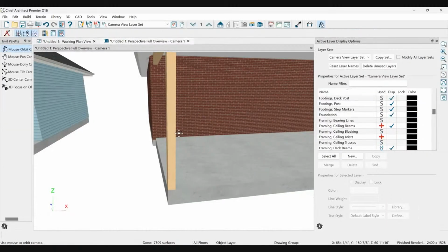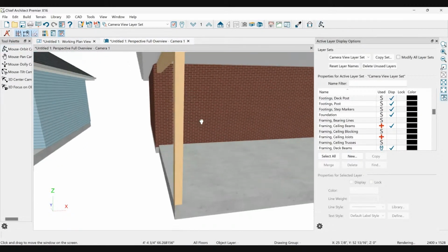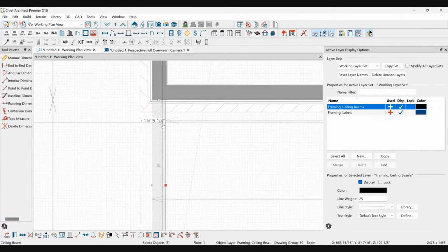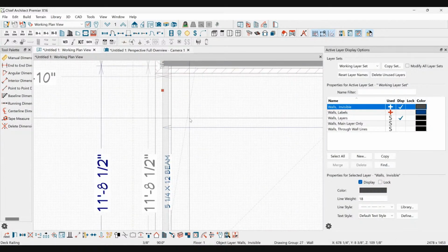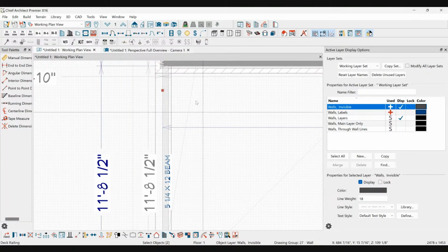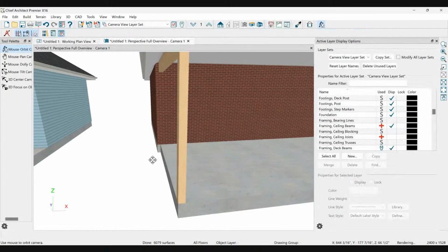And for me to control the computer, if you're someone who uses Chief and you want to know how to do this a fast and easy way, you're going to use the invisible wall right here, which is the representation of the beam. The wall's invisible, and you can actually open it up. In the settings of wall types, you go define it. In the wall properties, there's a section here for foundation offset. So if you specify -5.5, although I think in the computer it defaults to 4.5 for whatever reason, we'll just hit OK. It's going to automatically push the slab out, assuming the foundation rebuild is on.